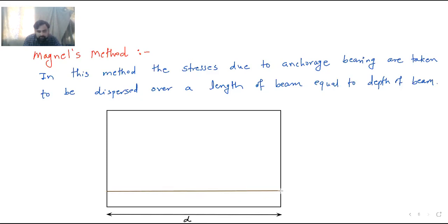This is the thickness of the tendon, the rod which has some diameter. Then we can see the plate. Here may be the anchor plate where we apply the stressing force, and this plate is the bearing plate.